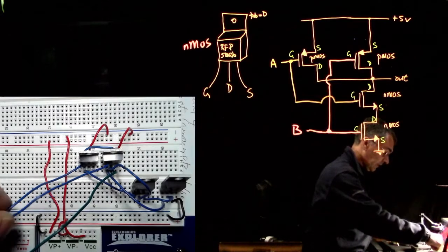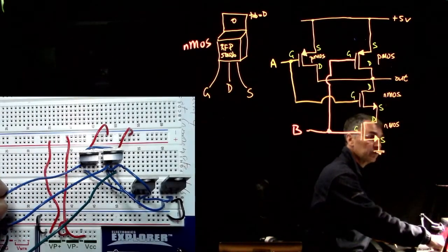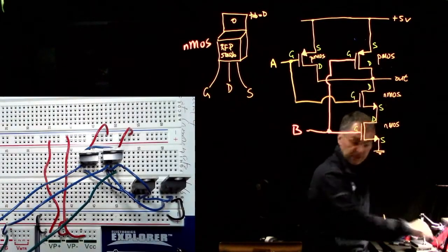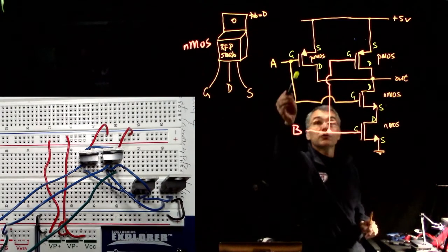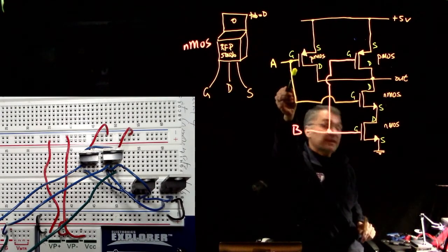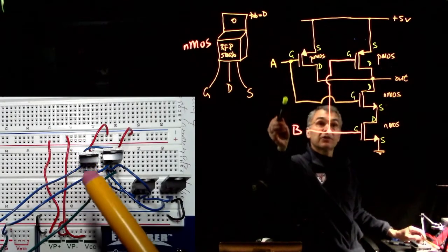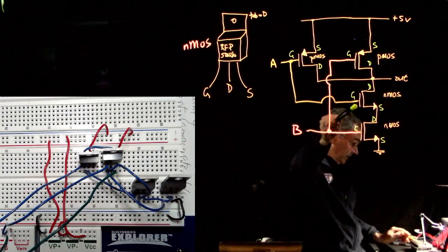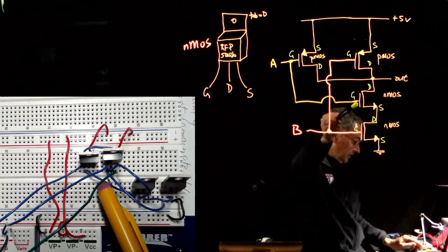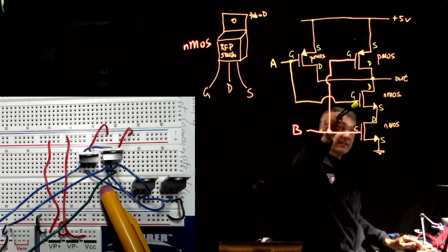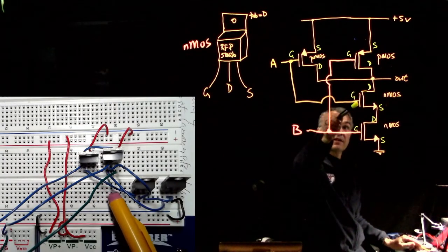So here is waveform generator channel 1, and it is going to this gate, the gate of the left-hand PMOS. And that should also be going to the gate of the left-hand NMOS, and it is because this little blue wire makes that connection from gate to gate.